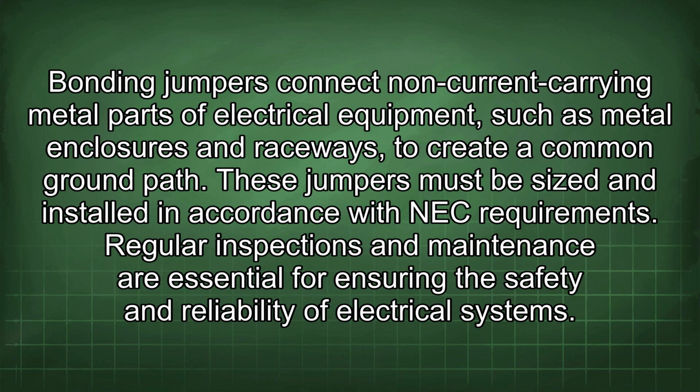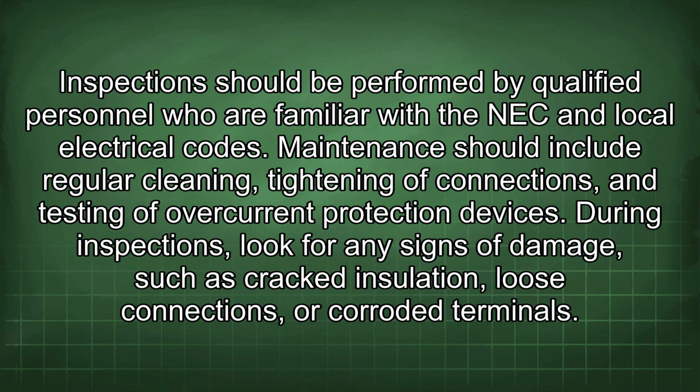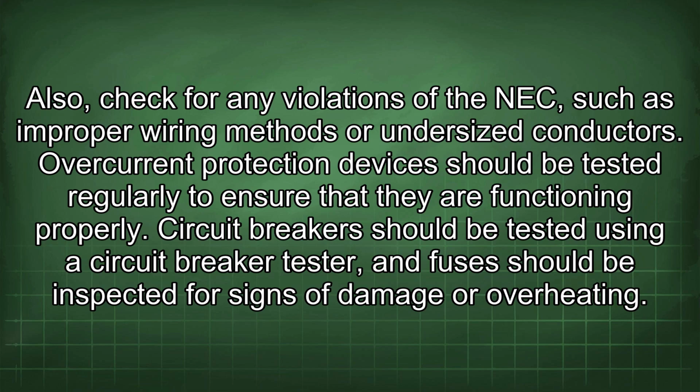Regular inspections and maintenance are essential for ensuring the safety and reliability of electrical systems. Inspections should be performed by qualified personnel who are familiar with the NEC and local electrical codes. Maintenance should include regular cleaning, tightening of connections, and testing of overcurrent protection devices. During inspections, look for any signs of damage, such as cracked insulation, loose connections, or corroded terminals. Also, check for any violations of the NEC, such as improper wiring methods or undersized conductors.